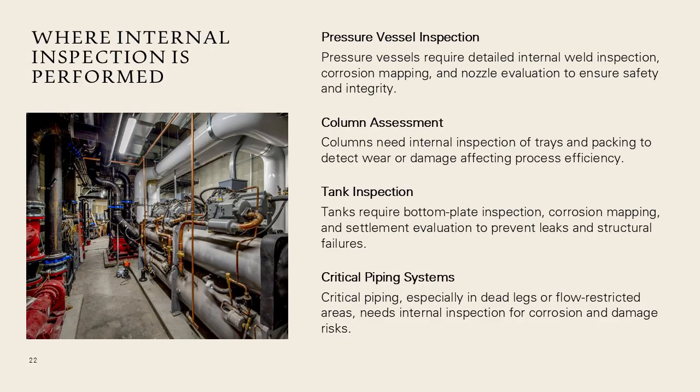Internal inspection may also apply to critical piping systems where internal corrosion is suspected, especially in dead legs or flow-restricted areas.